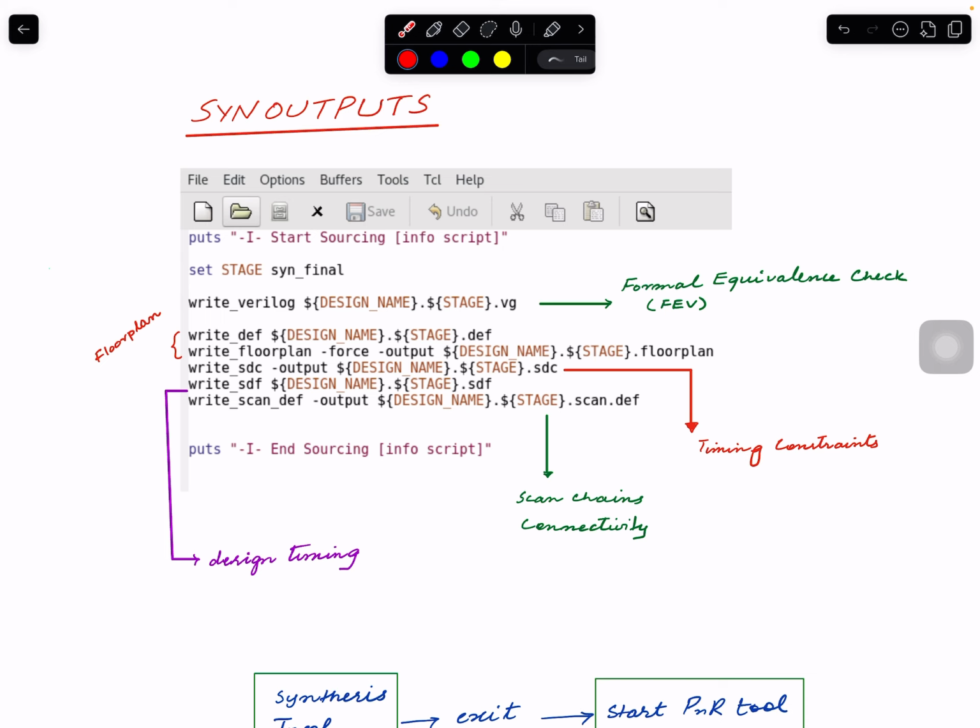I think that's good. When you're in a new tool, very quickly you will be able to learn what the new reports are. Just get all the commands that are used for report generation, and from there go to the man pages of each and get the description of the purpose of each report, and that will give you a good idea of what reports you can have in your flow.